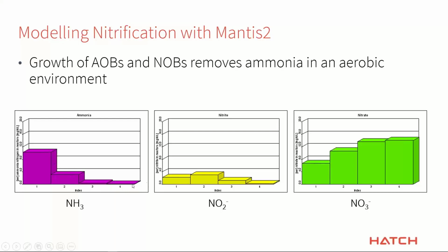The ammonia, by the time it leaves the bioreactor, at the end of that plug flow bioreactor, has been mostly oxidized away. So here's the nitrite and the nitrate. So it's generating that intermediate step of nitrite, and then the NOBs are also doing their job. They've got lots of air, they've got a growth rate, and whatever's being generated is mostly being consumed and then generated over here to nitrate. And so that is accumulating as you go down the length. Now, actually, in a lot of simulations, and even under our regular default conditions, this will pretty much be 0 in the middle. I actually had to back off the SRT and the oxygen a little bit so that it left a little bit of this hanging around so that I could use it for our demonstration today.